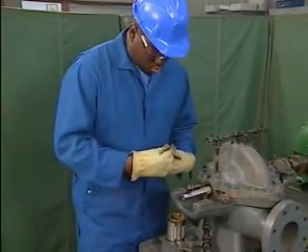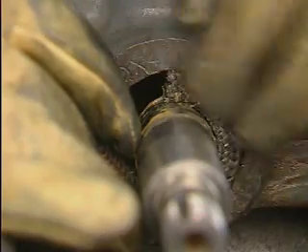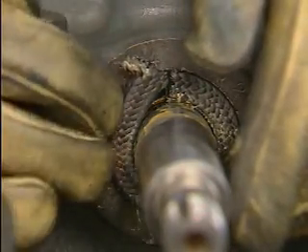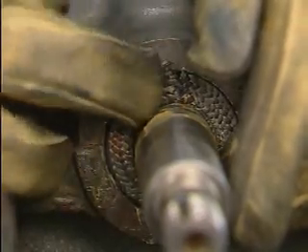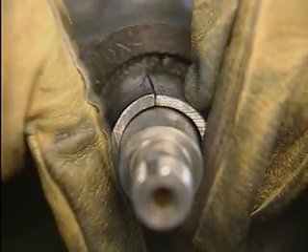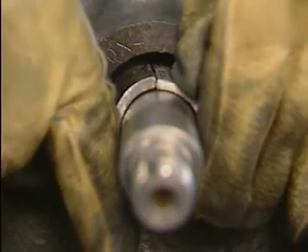After the mechanic lubricates the first ring of packing, he positions the ring in the stuffing box and seats it carefully. If the ring is not properly seated, it could be damaged when the next ring is installed. The best tool to seat packing is a split bushing. The split bushing fits inside the stuffing box and around the shaft. It allows the mechanic to seat the packing correctly.